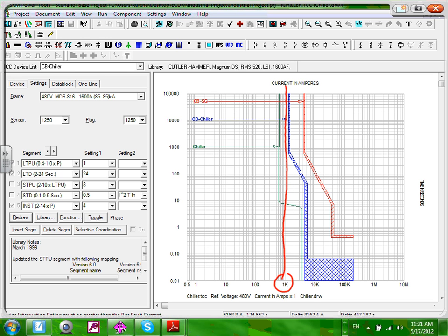So I have a ground fault here, a small ground fault that sits there forever. Why? Because this circuit breaker is sitting at 1250. Can you guys see why they have ground fault sensors? Because the current is high, but not high enough to trip. It can be seen as a load. So that curve does not reflect the settings in a way.